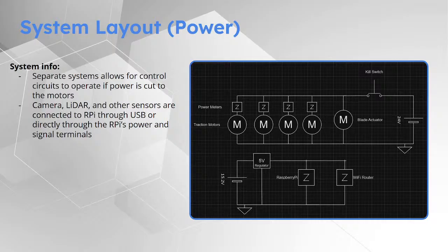So if you look at where the signal is flowing to PWM those motors, make sure that you've got a signal line and a return line twisted pair together. You need to shield and keep that area short. And then try to keep the single point ground near the motor, probably the best way to do that. But if you end up having multiple ties to your chassis or multiple ties to the plane, you're going to end up with